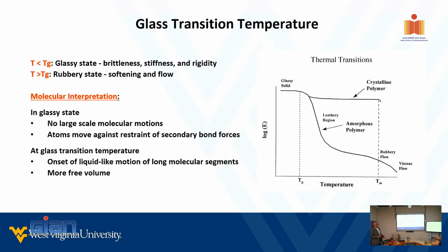Okay, I just talked about the glass transition temperature, and it's a slightly different way we presented the previous slide, and it talks about the glassy state, the amorphous polymer state, and the rubbery flowable state. So that's what, this is the most critical. So never ever even suggest a design of a structure in service going to be exposed beyond 180 degrees with FRP, unless you have a specialty resin.